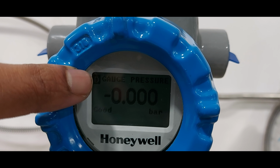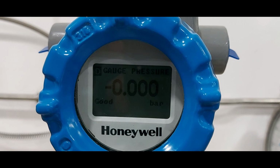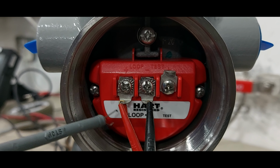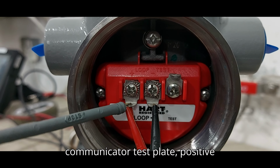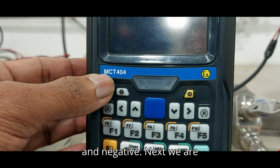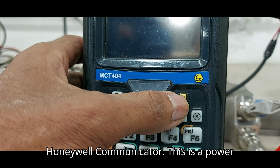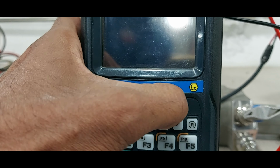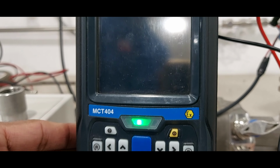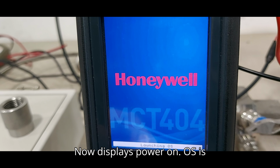That is enabled condition of low power. Next we connect the communicator test lead, positive and negative. Next we power on the MCT404 Honeywell communicator. This is the power on button. Now the display is powered on, the OS is loading.